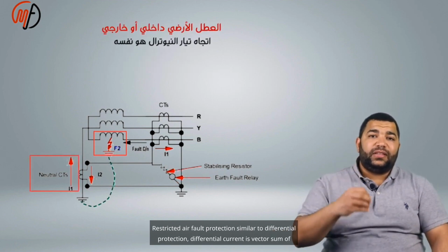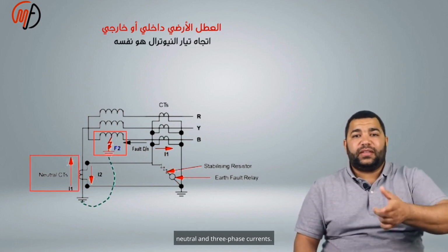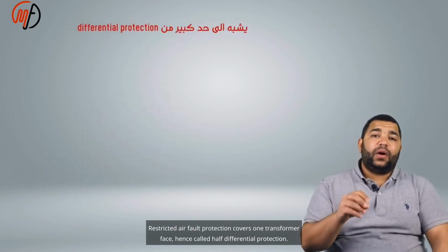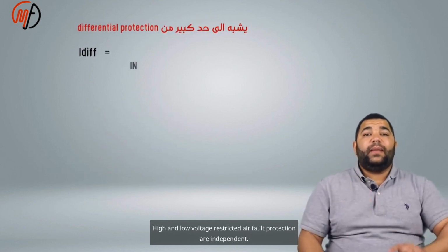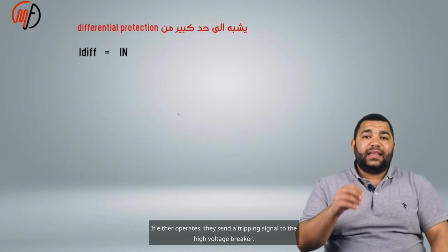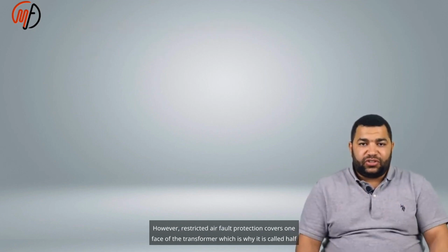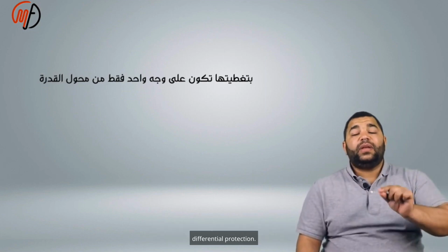Restricted earth fault protection is similar to differential protection. The differential current is the vector sum of the neutral and three-phase currents. Restricted earth fault protection covers one face of the transformer, which is why it is called half differential protection. High and low voltage restricted earth fault protections are independent. If either operates, it sends a tripping signal to the high voltage breaker.